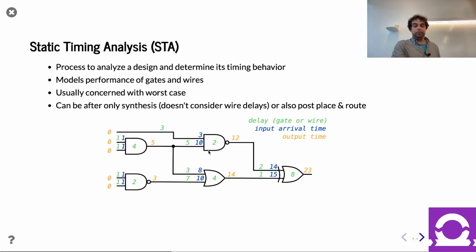Additionally, if we want to make this realistic for a real process, you configure things like what kind of margins you have in there for process variation or for temperature and that kind of stuff. And you put some margin in there. It kind of all comes together, right? But the result is, yeah, we have this time over here. And of course, as a designer, we're very curious about knowing what the critical path is so we can go about fixing it.